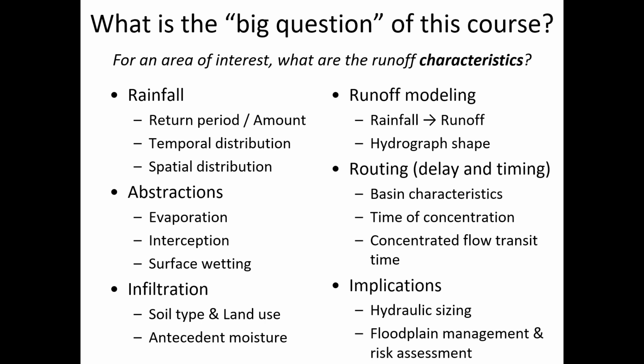So for instance, if you know how much damage is going to occur from a 5-year storm, and when there's a 10-year storm, how much more the damage is going to be, and the 25-year storm, what they normally do is develop inundation maps and knowing how deep will the water be and how deeply submerged would certain structures be at each return period.